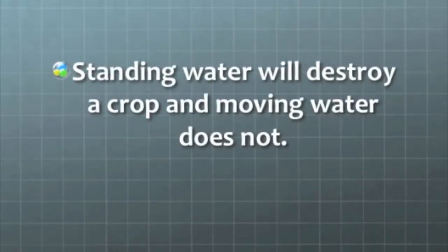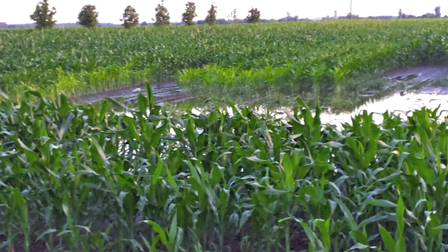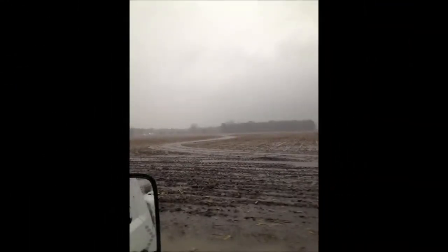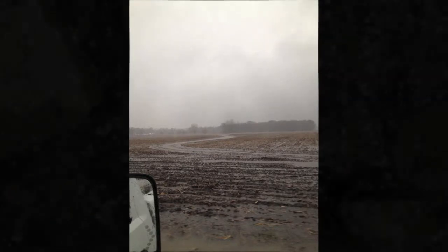A properly designed surface drain can eliminate surface water in a matter of hours rather than days. Have you ever seen standing water in your fields? When done correctly, flow channels have little if any erosion when using minimal slope just to get the surface water to flow rather than stand in the field. Natural soil contour lines of the water flow path does not allow the water to pick up velocity, which is a common cause of erosion.